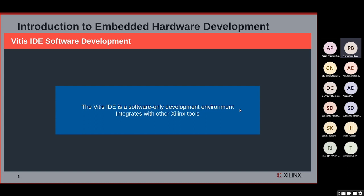VITIS IDE is only used for software development. We cannot do any hardware changes once my hardware files have gone inside the VITIS IDE environment. So that is the main thing that we need to remember. All hardware changes will be done in Vivado only. Any kind of software changes will be done in the VITIS IDE software development.